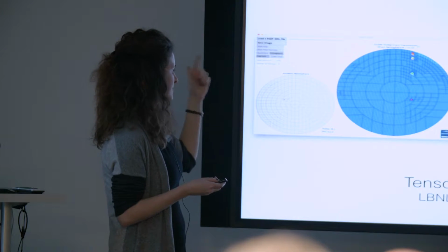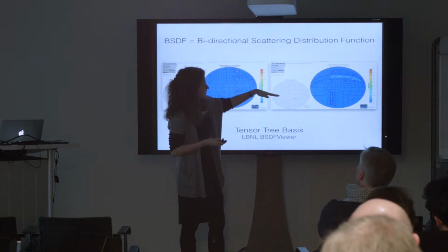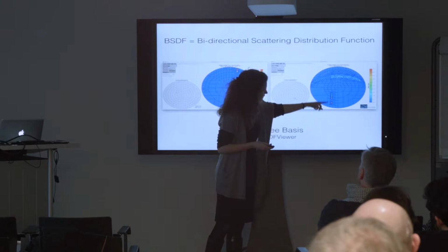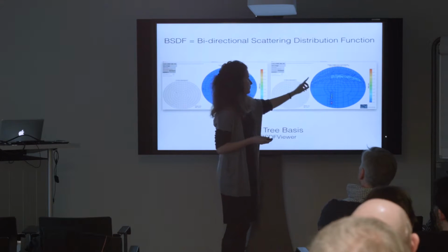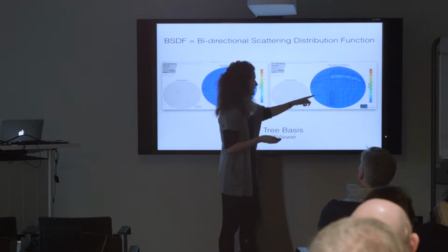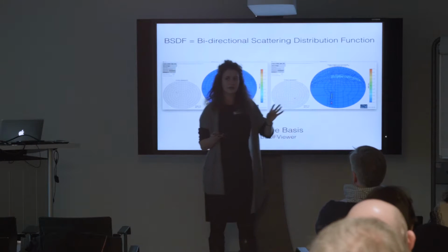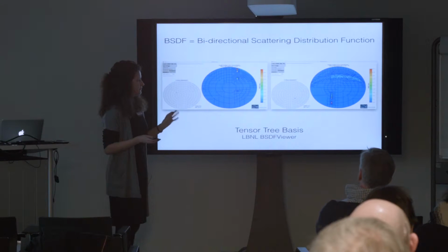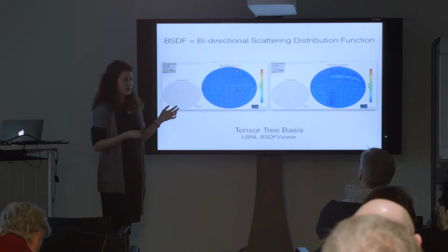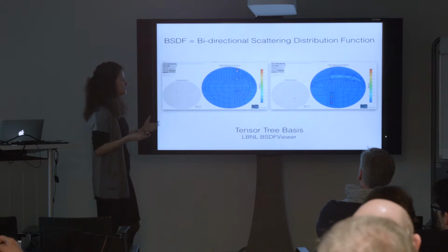So, for example, this shows something like slat blinds. We get something diffuse at the top and a specular bit here. So this description is not a matrix anymore, but it's a variable resolution description. Here it's getting finer because it needs that, and here it's remaining coarse because it doesn't need that big accuracy. So in this way we are reaching a good accuracy, but without having too huge files and too much overload on the computational expense.